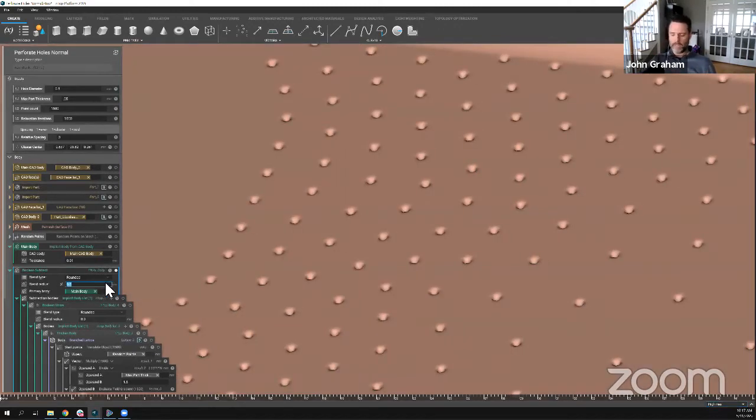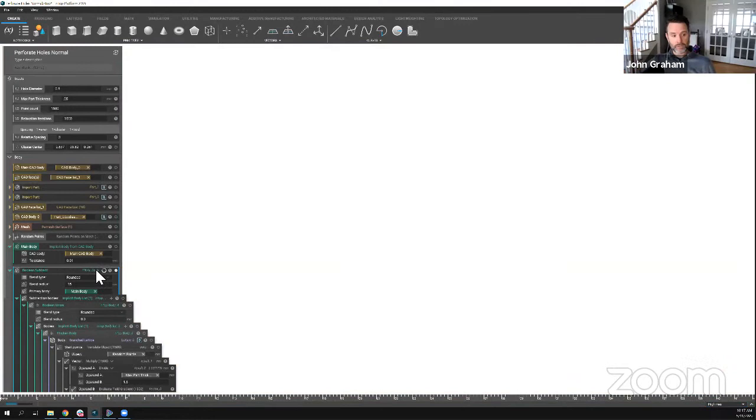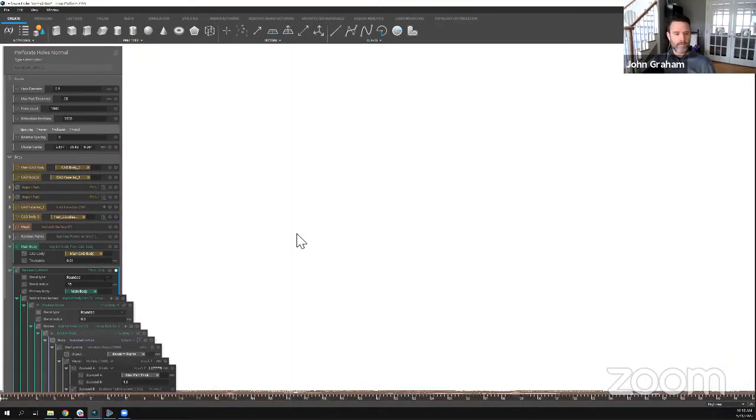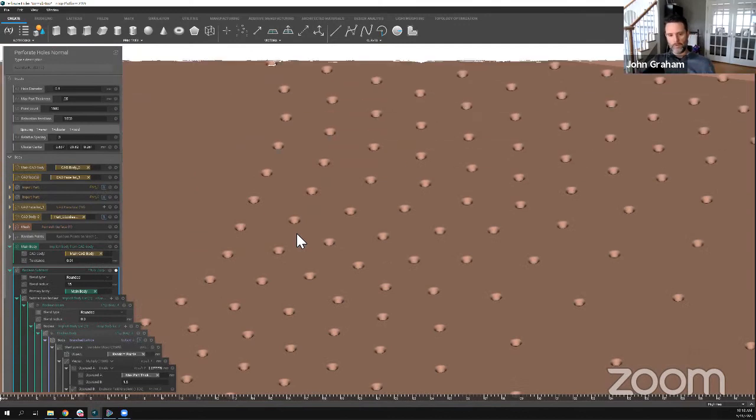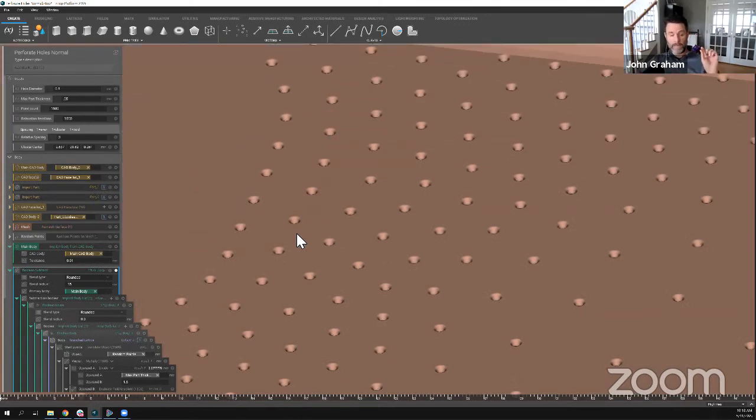That can be a complex operation in traditional systems to actually remedy that and put a round on it. Here in nTop, I change a variable, and now I've got a radius that's actually bigger than the depth, 0.15 millimeters, and I've got a radius all around there. So again, you're holding your phone case, and you're going to have some bumps on your hand.